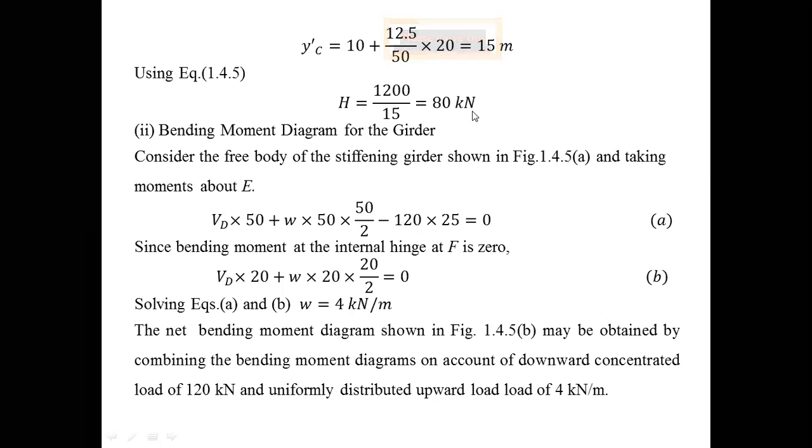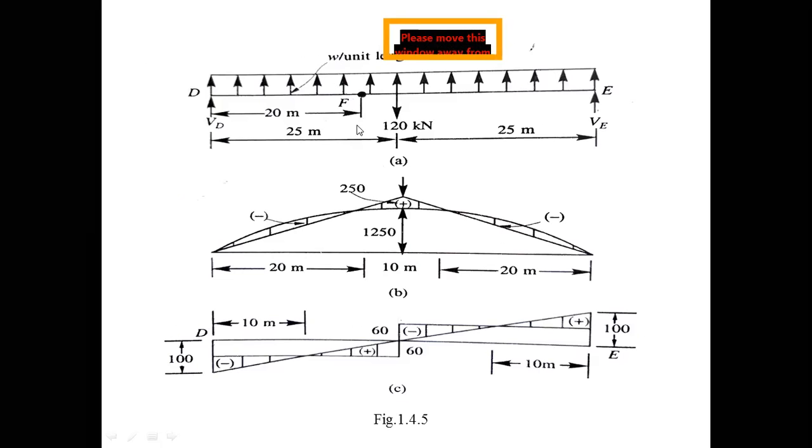And now find W. You don't know how much it is; once you know the horizontal reaction, then you determine W also. So how do you calculate W? Taking bending moment for this problem, taking bending moment at E, take the free body diagram for the simple beam, acting as a simply supported beam. Therefore, it is a hinge support at D and a roller support at E.